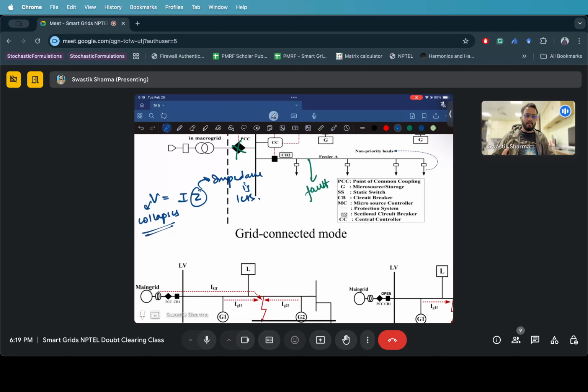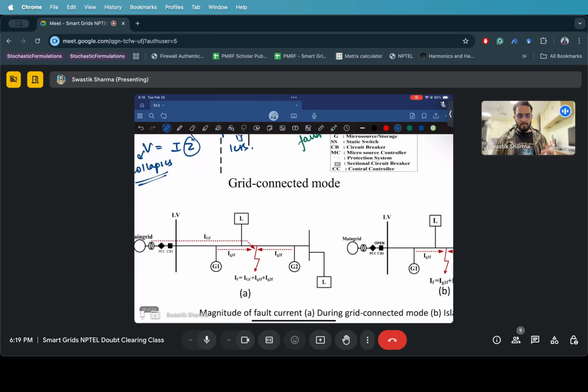So from the grid's perspective, I see that voltage is collapsing at that node. The grid starts applying more power to make sure that the voltage at that node is not collapsing, or not going beyond its operating limit. So we supply to the maximum value we can, and that is precisely what happens.